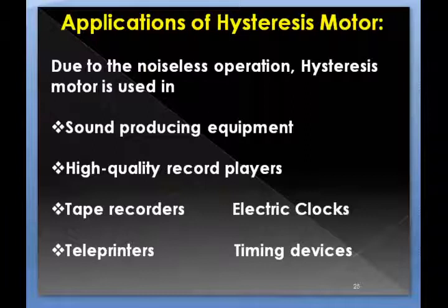Lastly, I discuss the applications. Due to noiseless operation, the hysteresis motor is used for sound producing equipment, high quality record players, tape recorders, electric clocks, teleprinters, timing devices, etc. Some images are here.